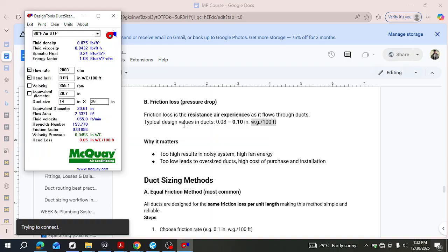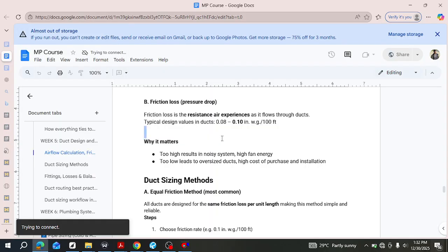It usually helps for lower friction, right? But that won't always fit into spaces, for example when you're putting the ducts through a floor that divides two floors, basically not a ceiling. If it's in a ceiling on an attic space, you can size the duct as big as you want, right? You can try and get that square size as much as you want. And in some cases you can even try to select circular ducts, right?